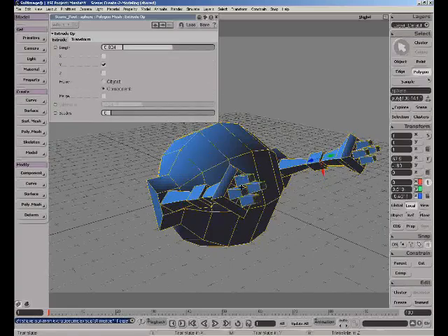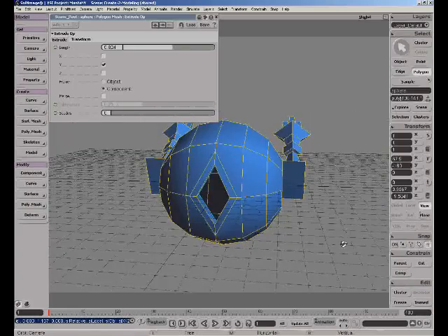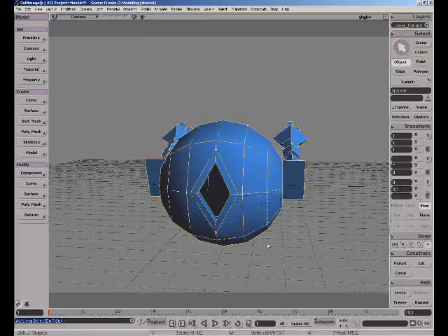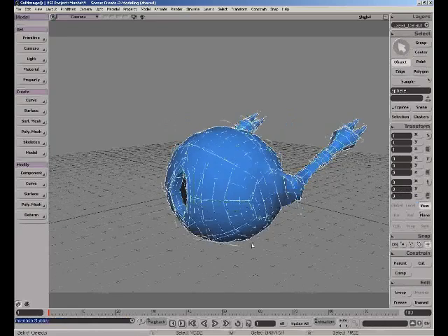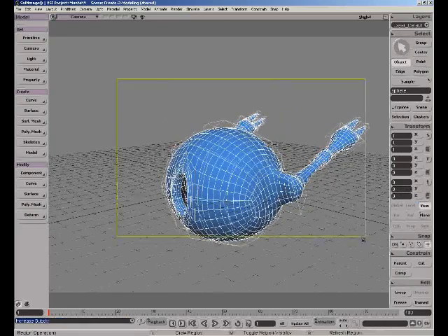You can see now I've got the edges aren't shared anymore, like so. And now I can continue to, say, extrude those out, and that is now where this will attach to the wall. So let's go ahead and close this up like so, and just kind of take a look at what we've built so far. Again, at any time, I can press the plus key a couple times. Again, that's where I've mapped my subdivision level to the keyboard.